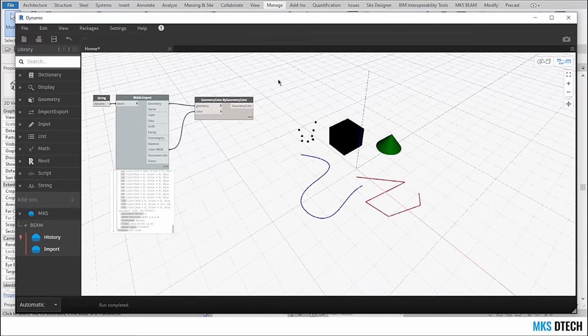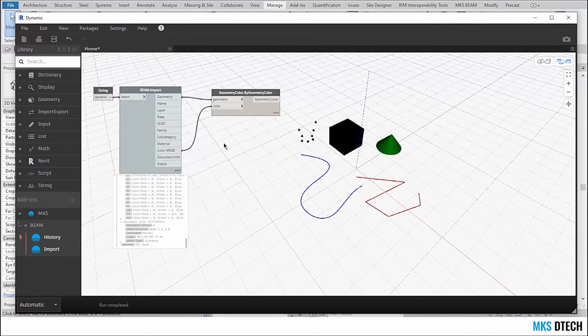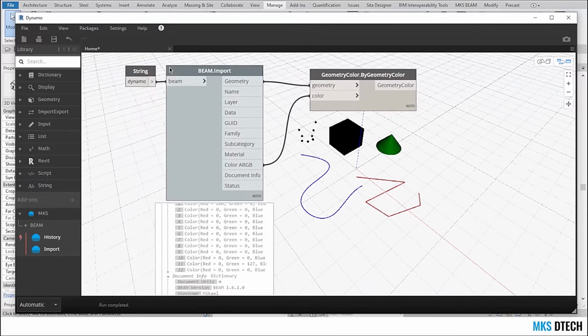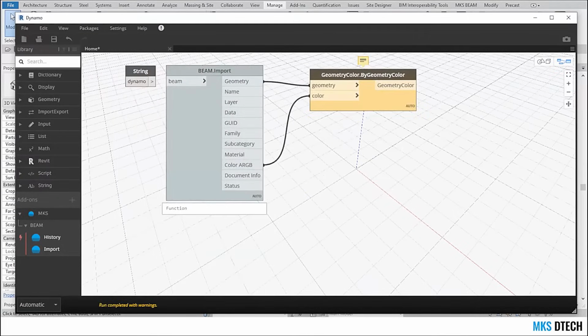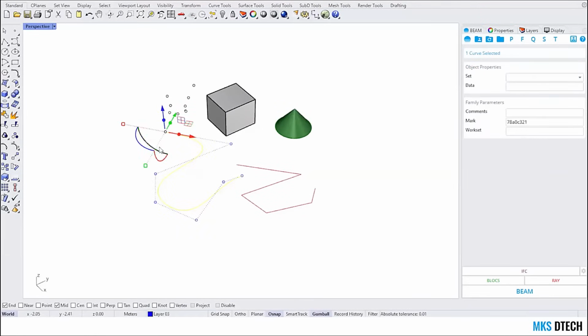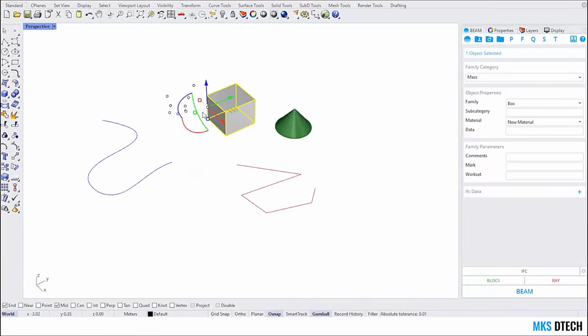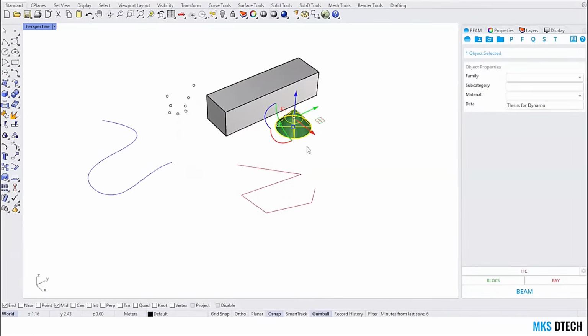I can pick some points and create some levels using the Z of the points, and all the workflows that are available with Dynamo. And we know, so we just need the primitives. We just need the surfaces and the points and the curves to make those objects and create them straight from Rhino. What is nice is that if we unplug this and I make a change to this geometry, for example, let's move this out and make this a little bit bigger and move this.